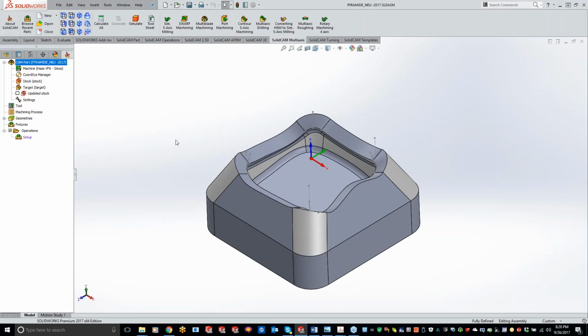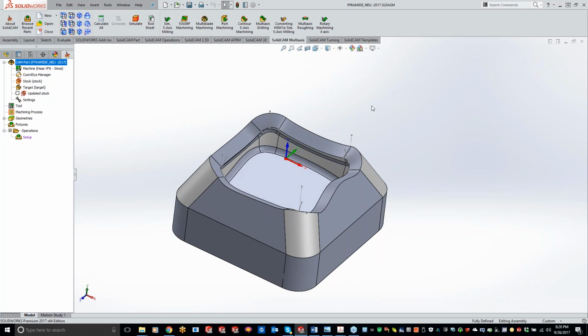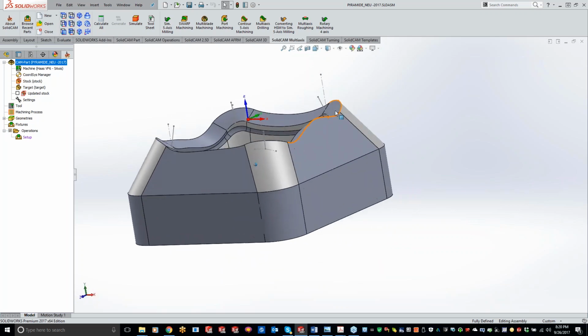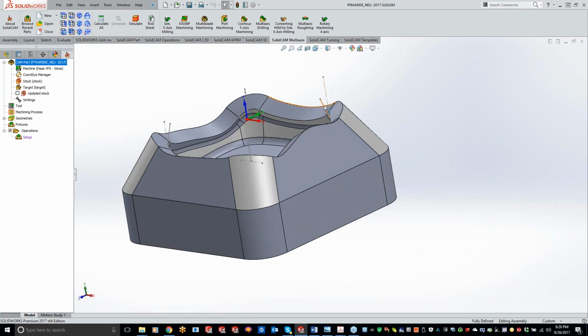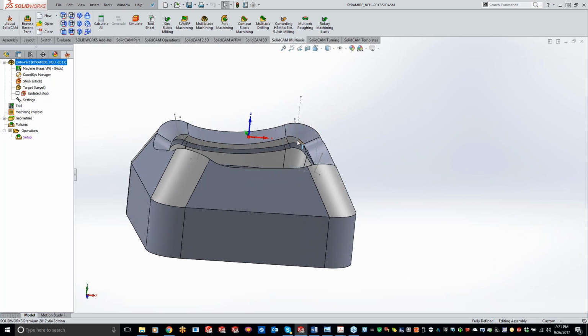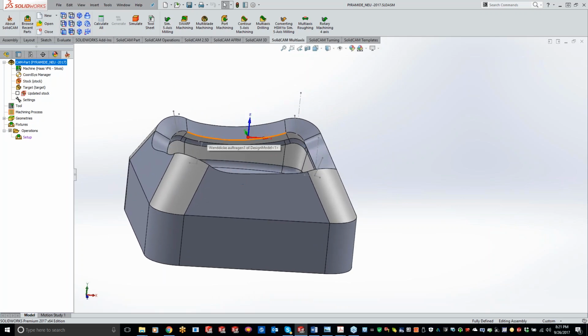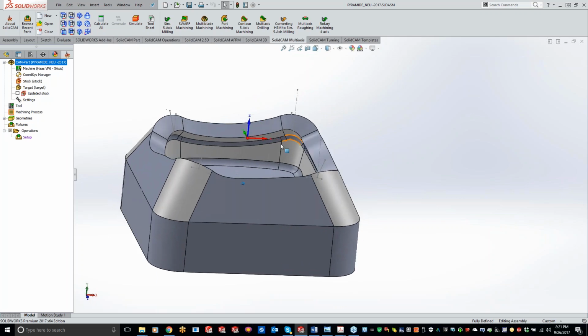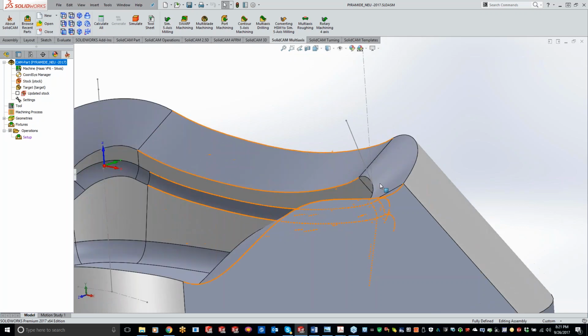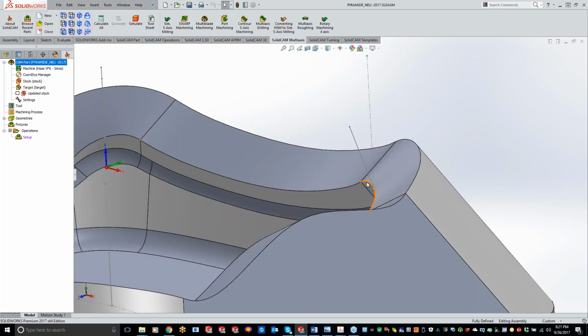Okay, so here's one where we're not so much doing a trimming, but doing a chamfer around. Now, the one really cool thing about this, and this got brought to my attention today with Ken, is that we can actually get these lines pointed in any direction. We don't have to have these lines set up just to follow the outside perimeter, but if I have my lines set up that way, let me get an angle shot. You'll notice that I'm not going to be able to get a chamfer around the outside perimeter right on this edge.